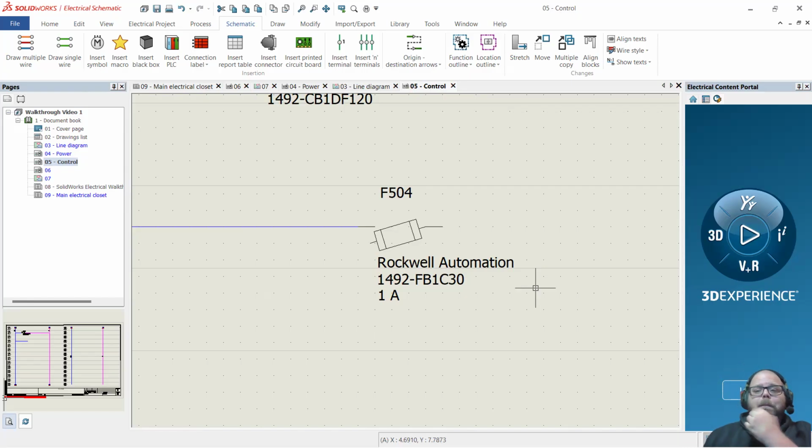I would much rather, on the schematic, not care what the part number of this fuse holder is. I care what the part number of the fuse is for schematic purposes. Troubleshooting, I've got it in my hand, staring at a machine. I can grab the right fuse based on my documentation and pop it back in there. Especially as I get older, my eyes aren't so good at looking at the little engraving on the glass fuses that tells me what current rating they are. So a schematic telling me a part number helps.